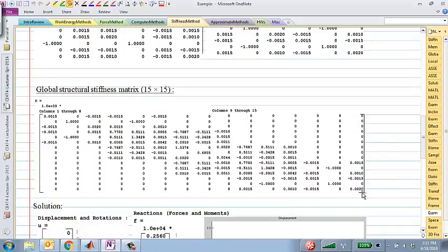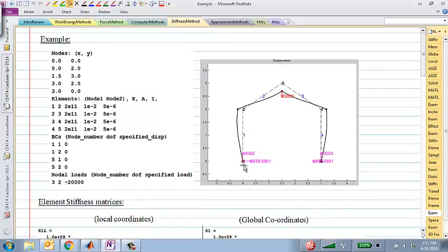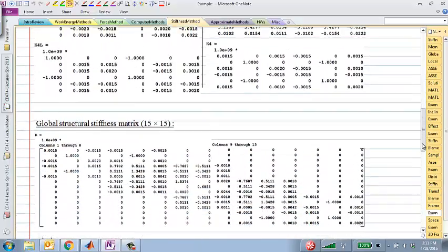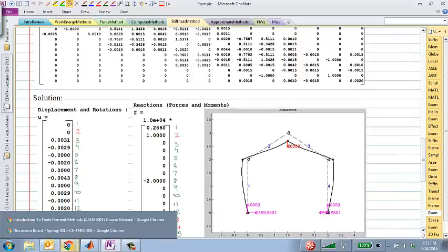Assembly, you get a big huge 15 cross 15 matrix where how many degrees of freedom are free and how many are fixed for this particular problem? This is a pin and a pin. So out of the 15 degrees of freedom, how many are free, how many are fixed? Say that again. That's right. 11 free, and indeed 4 fixed because 2 degrees of freedom, X and Y displacements, are fixed here. The rotation is indeed free. So that means that ultimately we'd be solving an 11 cross 11 system of equations, which of course MATLAB solves for us in no time.